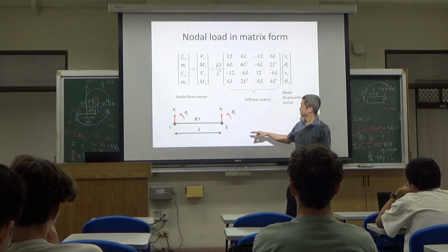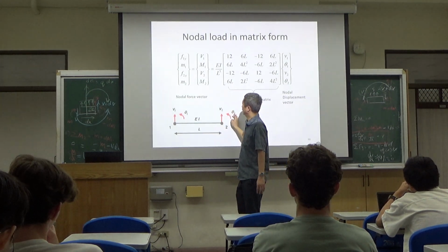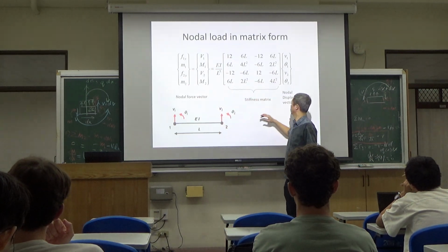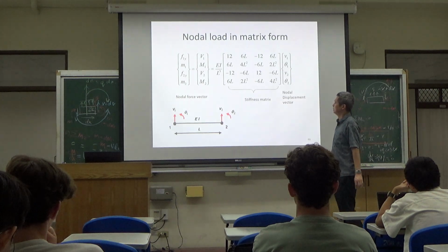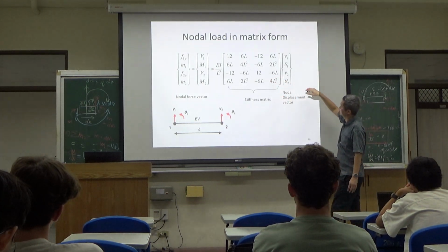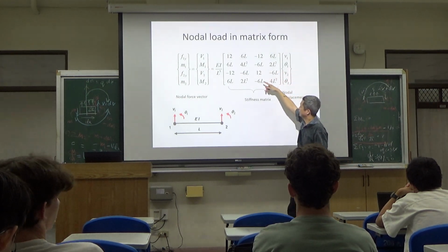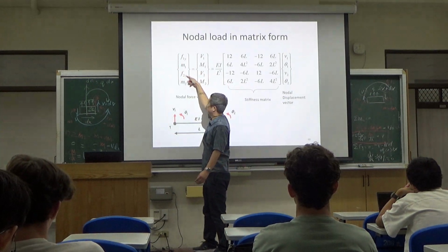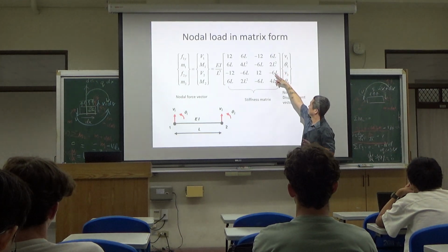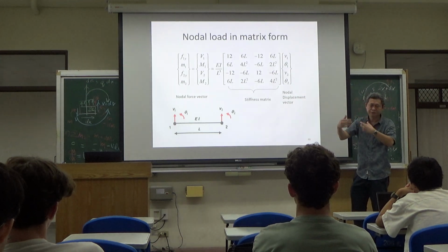Likewise, the force on the right node, node 2, as well as the moment on node 2, can be expressed as a function of the boundary value, but the coefficient is opposite. So you can see here, is this element balanced? Yes. Why? F1y plus F2y is 0. When you do the checking, you do the sum of these two rows. They cancel each other.